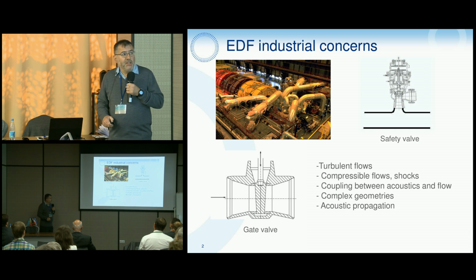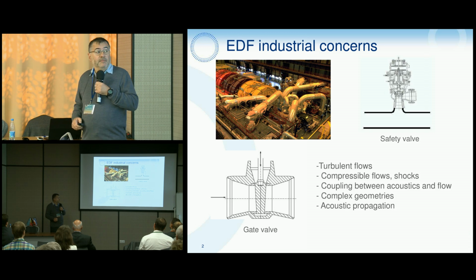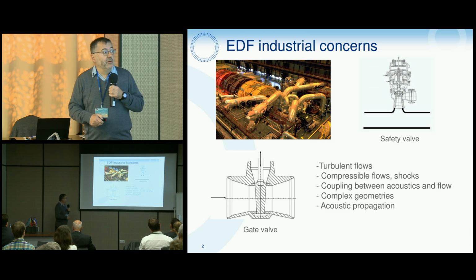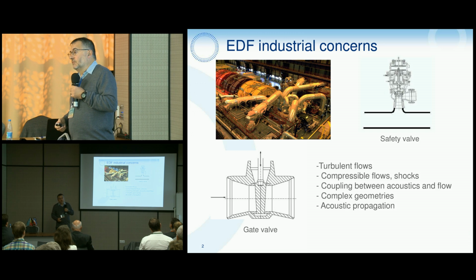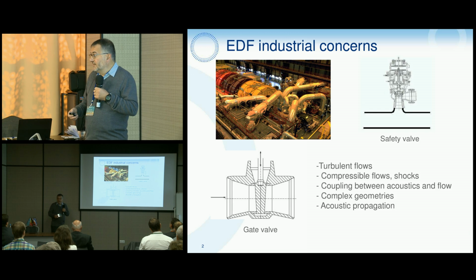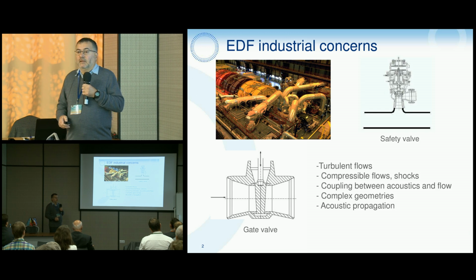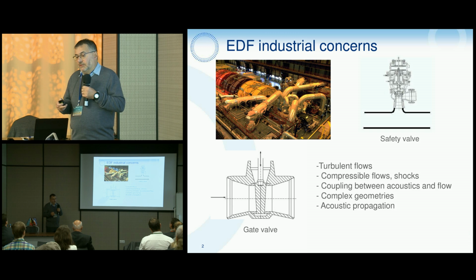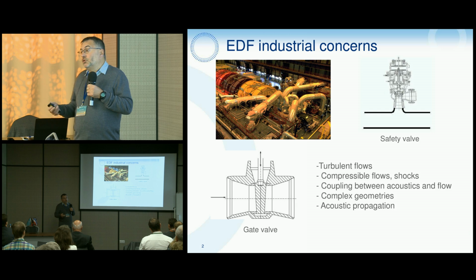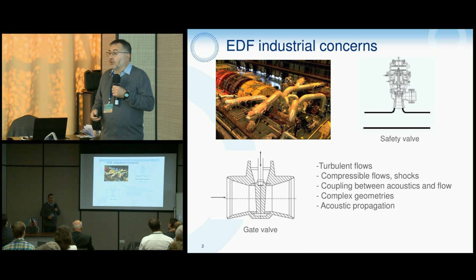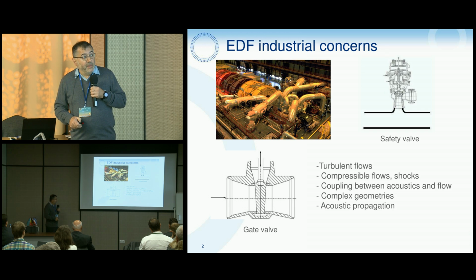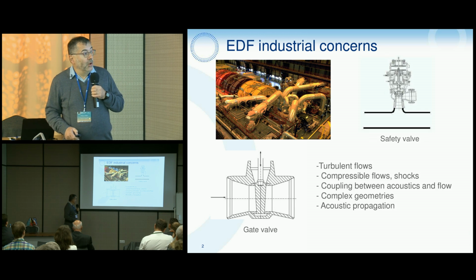In such situations, we have to deal with turbulent flows, with compressible flow, shocks, because downstream of a powered valve, the flow is transonic, very non-stationary and so very sensitive to coupling with acoustic resonances. So one of our main concerns is the coupling between the acoustics and the flow.